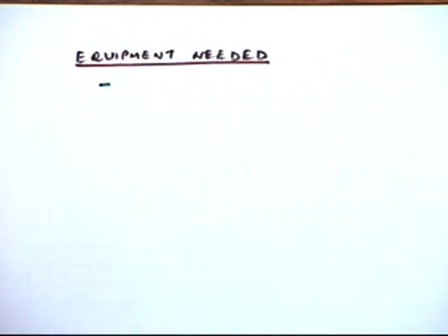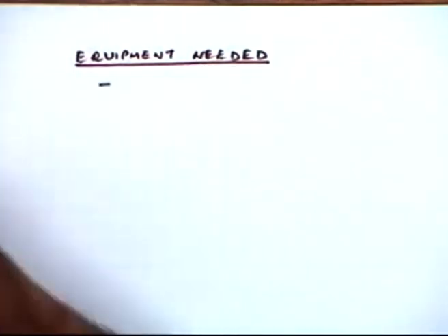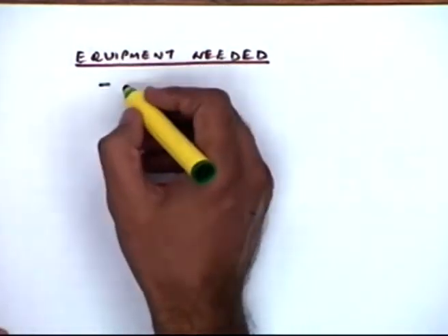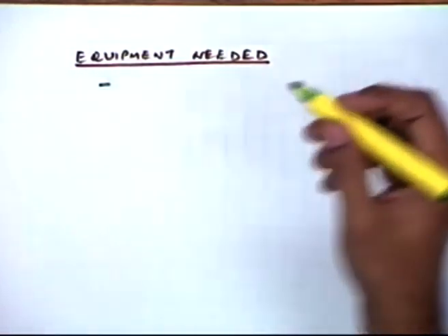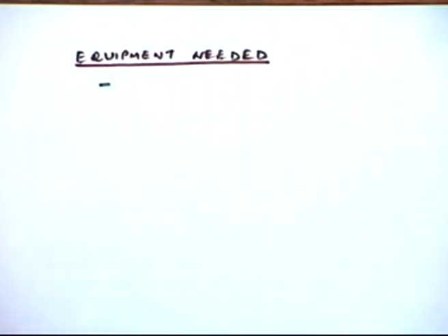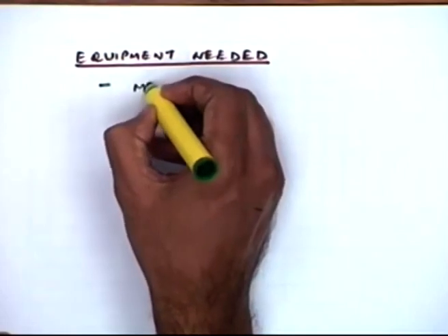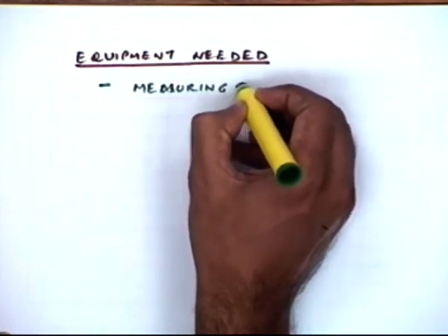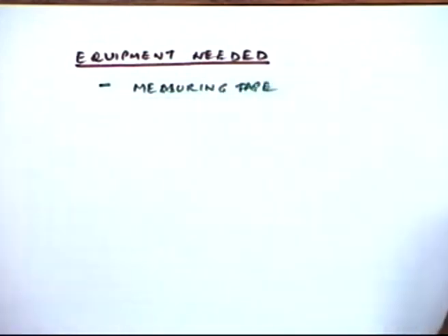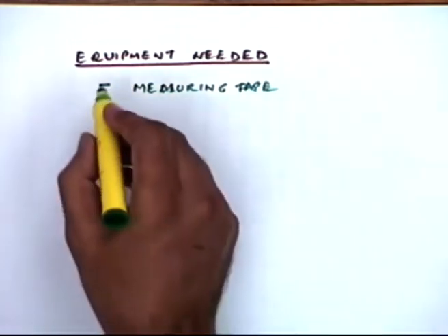There will be some which will be needed, we might not be including them, but you have to have some measuring tape, because you will have to find out what is the width at different locations. In some cases, if the ridges are not parallel to each other, you can only check by using the measuring tape. So you should have some measuring tape. Maybe a 30-meter tape can be sufficient.